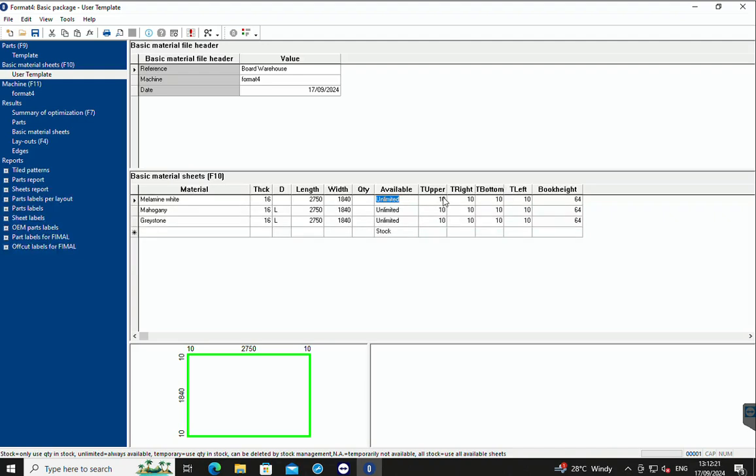If you make it smaller, your offcut is going to fall into the gap where your blade needs to go up and run, and that can damage the machine and causes a clog up of offcuts in the cutting blade or saw blade gap. So always recommended to use 10 on all these fields. It's a good value to save your machine on maintenance.